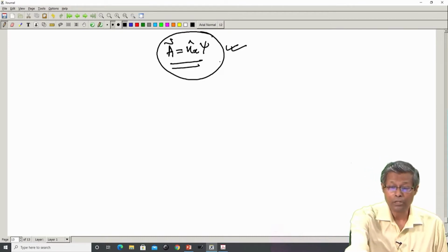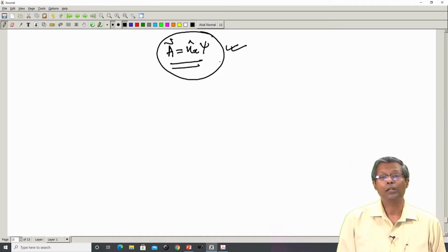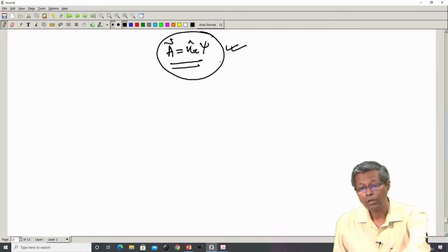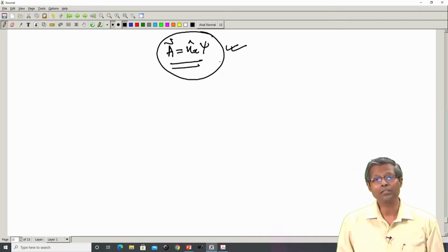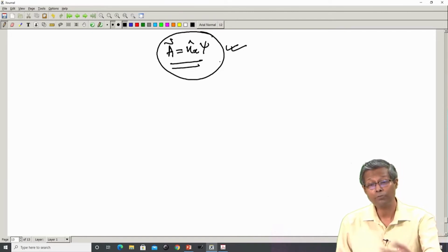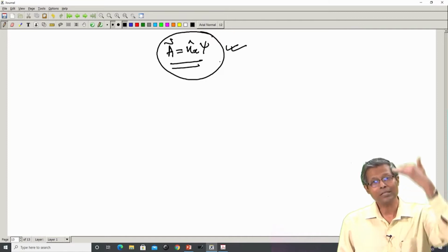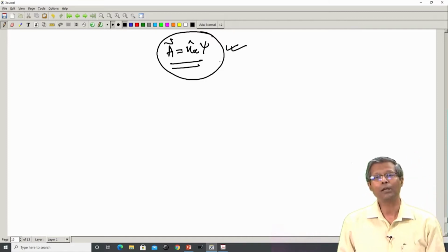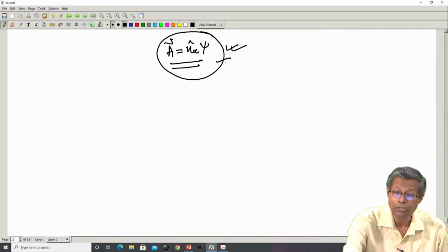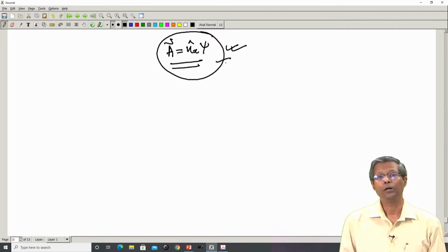Therefore, this equation characterizes the LSM modes, and we have already derived the relationship between the psi function and the electric and magnetic fields for this mode, or we have expressed the electric and magnetic fields in terms of the psi function for this kind of substitution before. So, we will use exactly those electric and magnetic fields resulting out of this condition of the magnetic vector potential, which characterizes the TM to X mode.